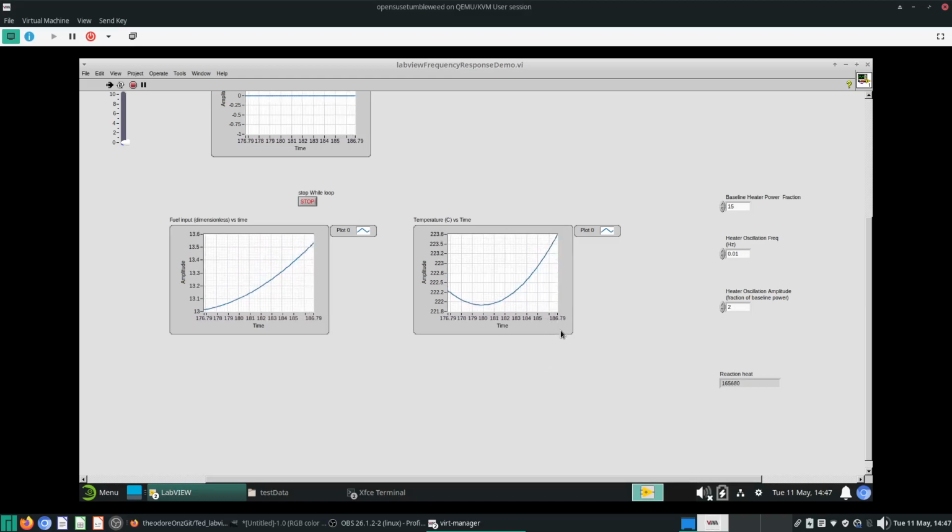So of course I'm going to let this thing run for a while, maybe let it run to about 1000 seconds, and let's see what happens. Yeah, I can see frequency response testing in a real system. If you are talking about real reactors, step response is easy, but if you have a chemical reactor, you need to test at very low frequencies to do the control system. Then of course you might want to use step response, or some other kind of inputs so that you can test these things quickly at multiple frequencies.